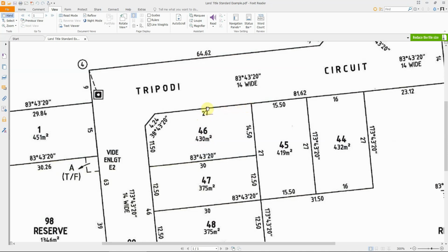For the parcel segments, we need to show the distance of each segment, or the length of each segment, and the bearing for it. And for the distance, we're showing the distance in meters with 2 decimal digits. So let's work towards this format.